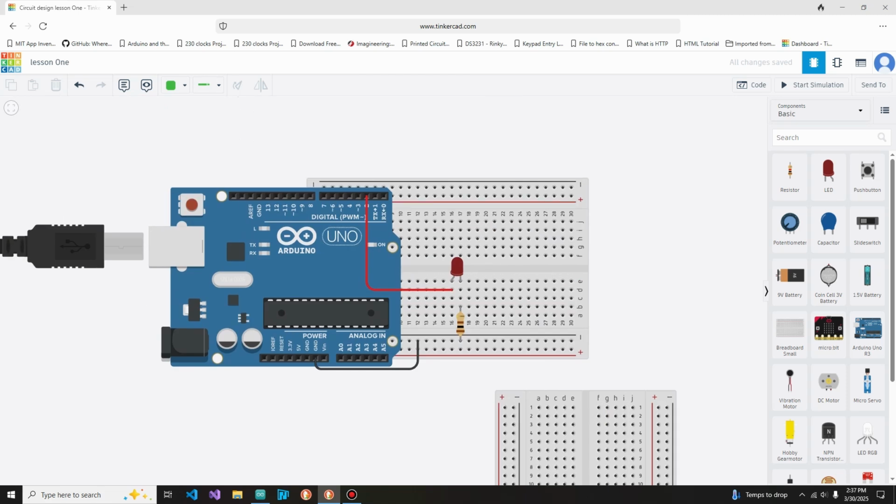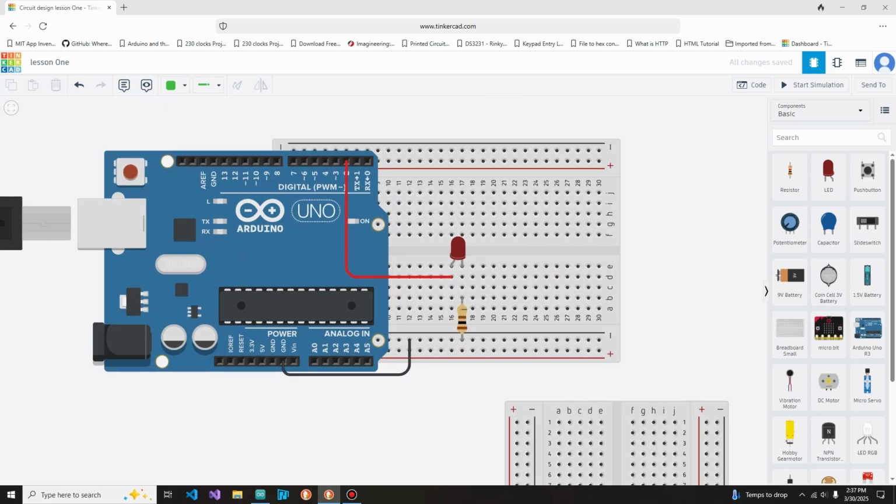Now let's pull up over here onto our Arduino. This is how we're going to set this up. And as you remember, we used pin 2 in the Arduino IDE to signify what pin we're going to be using. So we have it here on pin 2, and we have that pulled down and around onto the anode side. Now, if you don't know, the anode is positive and the cathode is negative.